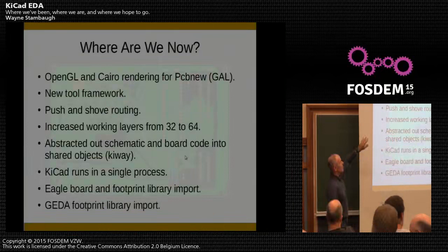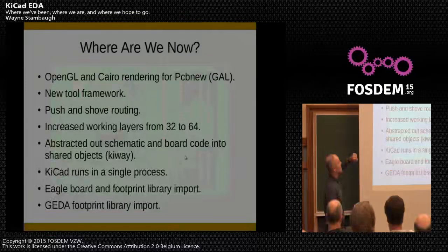So we now have OpenGL and Cairo rendering just in PCB-new. That has not been ported over to the schematic editor yet. There's the tool framework, which I talked about, which makes it a lot easier to add more complicated and interesting tools to the schematic or the board editor. And push-shove routing, which Tom will talk about.